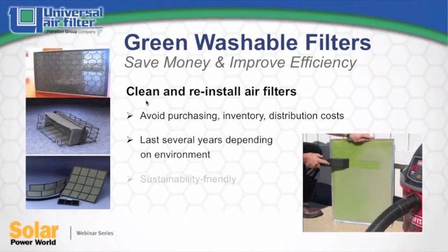Washing filters is easy, and most times you can clean without the need for water. Just use a vacuum as shown, or blow out with compressed air to clean and reuse. Saves on purchasing, logistics, and storage, and the filter should last at least a few years if environments are not overly corrosive.